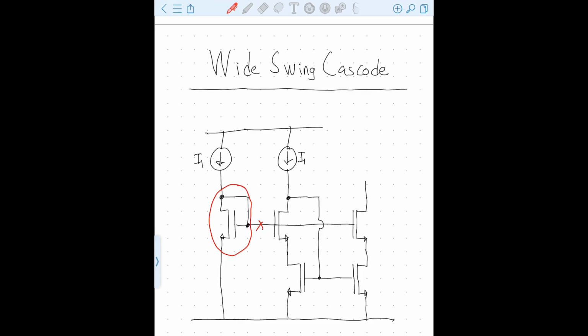We can actually break this connection and apply a voltage to some potential to induce a VGS drop across the other two cascode structures. And in doing that, once again, we are sensitive to the parameters of those devices, because the voltage V1 over here is going to be more or less uncorrelated to any of the parametric variations upon those two devices.